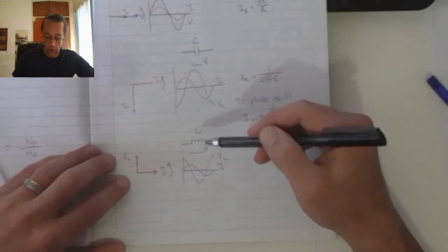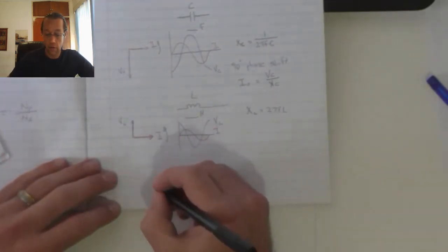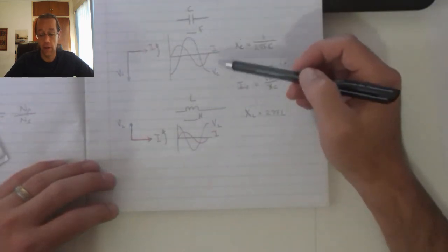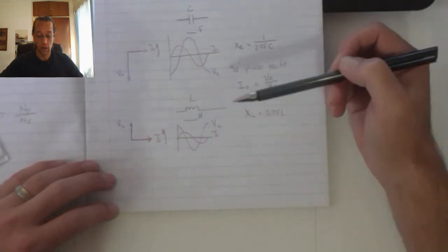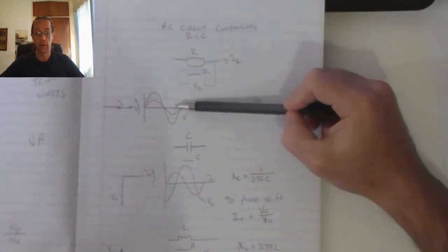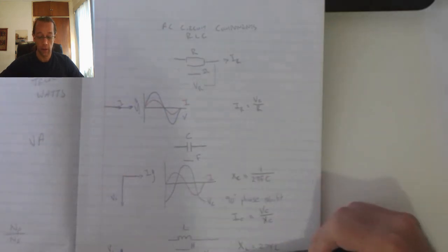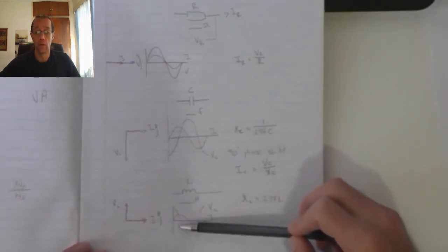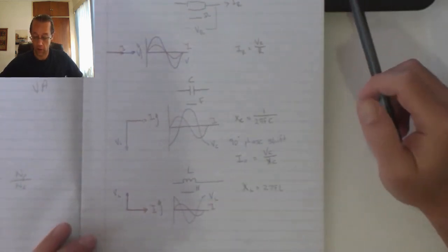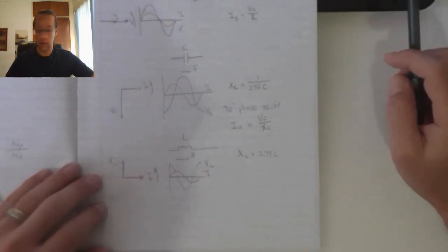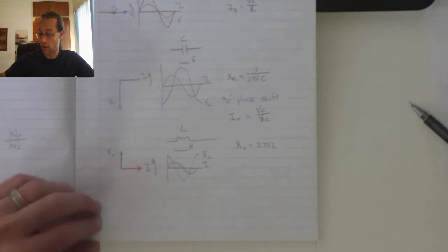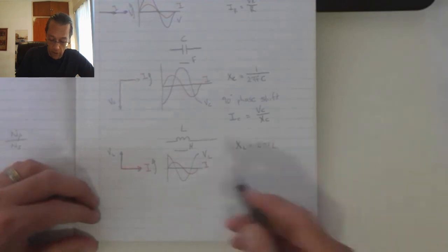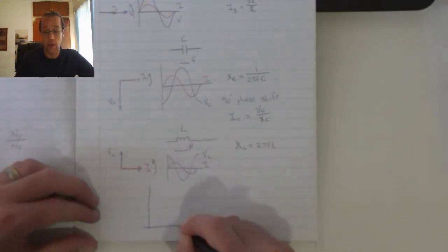Okay, so to summarize, if we compare the voltage and the currents, because this is a series circuit, because all these components are connected in series, we are going to have a constant sine wave for the current. The voltage, on the other hand, is going to separate over each individual component in accordance with Kirchhoff's voltage law for series circuits. If we look at the effects that a range of frequencies is going to have on my RLC components, we can represent that as a graph.